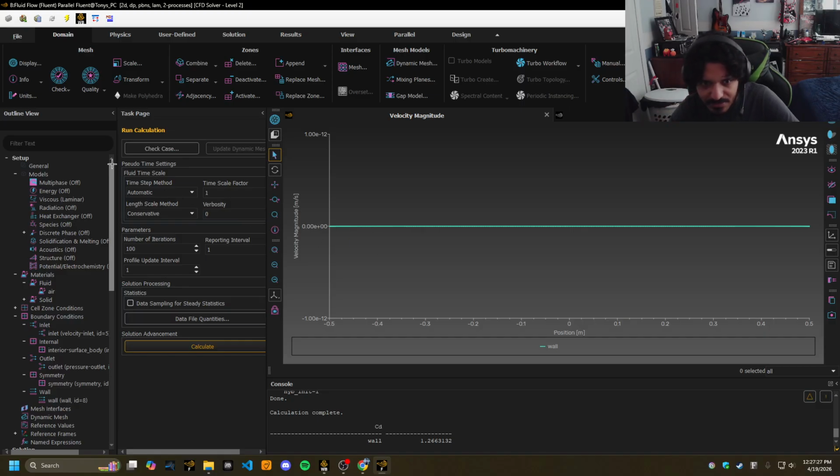Drag coefficient. And then lastly, in order for a viscous turbulent, we can just use a higher velocity in relation to the Reynolds number. So for me, I'm going to use, let's say, 50. Double check that it's in the turbulent region. Yeah, that is very much in the turbulent region for 50 meters per second. It's above 3 million Reynolds number. So it's definitely in the turbulent region.